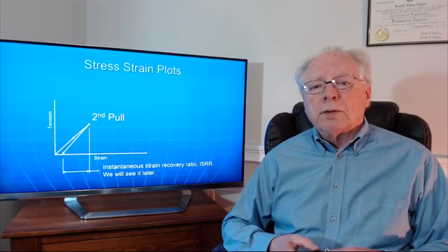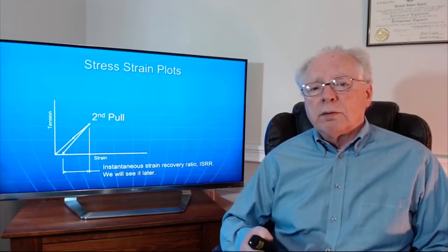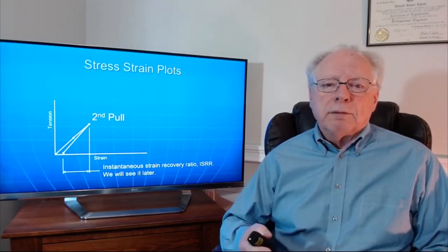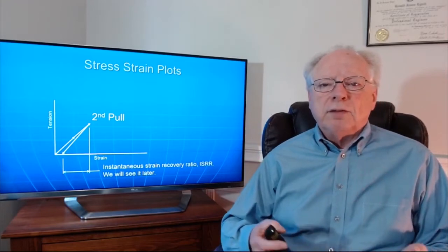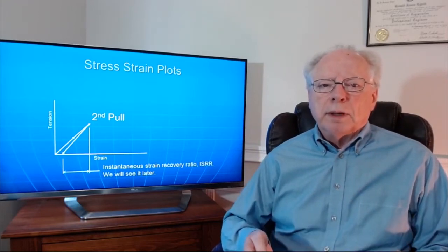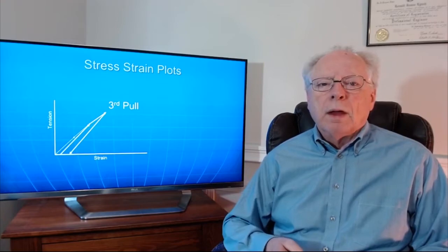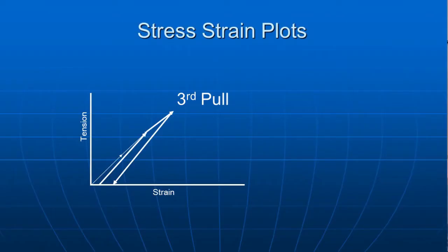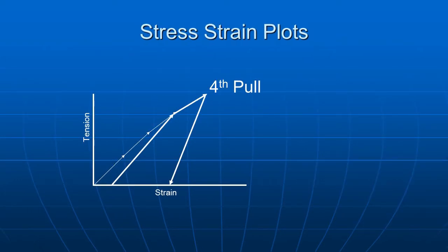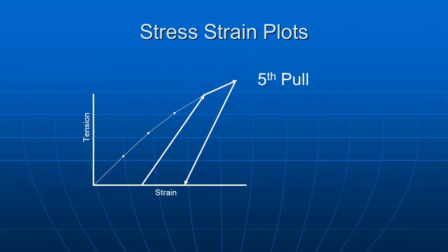When your web goes from high strain to low strain over a driven roller, it needs to recover very quickly. This test gives you an idea of the web's ability to do that. We can keep going with a third pull. Again, watch the strain recovery ratio. And a fourth pull. And a fifth pull.